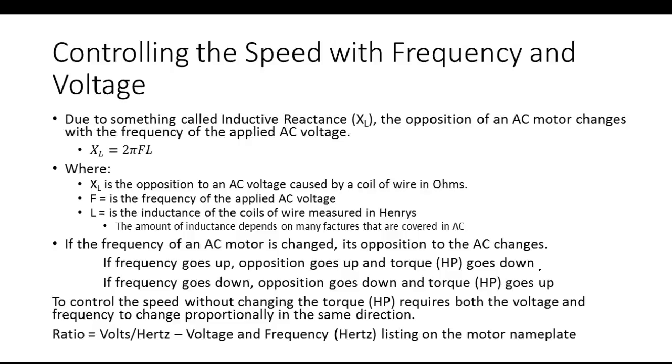So basically what you do is you just enter that information. Anybody ever programmed a variable speed drive? Most of the time you just take the information that's on the faceplate and then punch that into the thing. And then of course you've got other things you can do. You can set up the acceleration rate, how fast it accelerates.